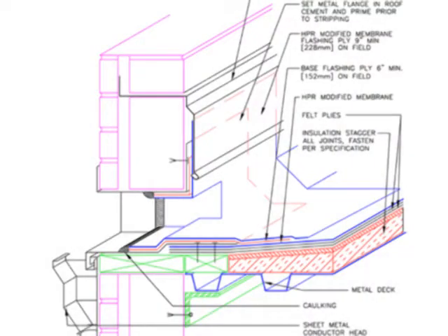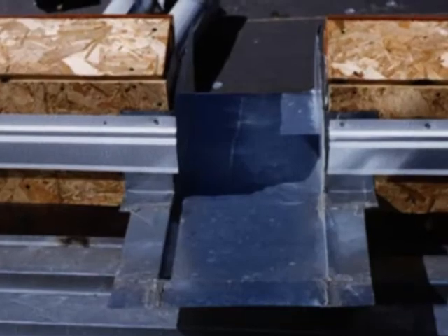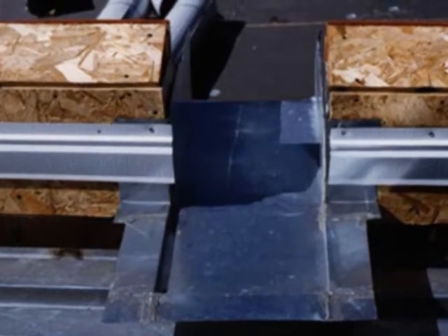Typical installation of the through-wall scupper includes the following steps. Inspect the nailer to assure proper attachment and configuration. Run 1 ply over nailer into scupper hole and up the flashing as in a typical wall flashing detail. Assure coverage of all wood nailers. Install a scupper box in a 1/4 inch bed of mastic.